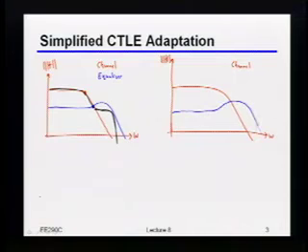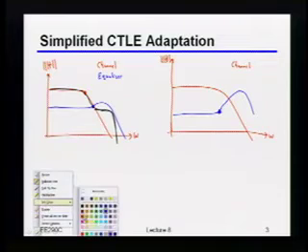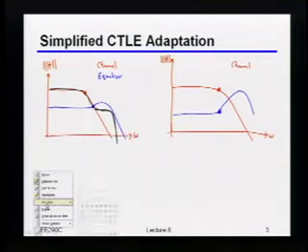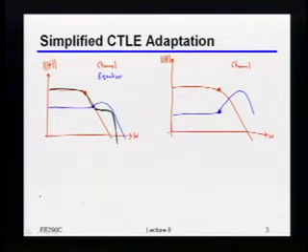The equalizer will now look something like this. There. In other words, that's the 0 of the equalizer, and that's the pole of the equalizer. Okay? All right, so now my equalized response should basically just look flat, right? If I do it properly, then the magnitude will be lower than the previous case. So it should look something like this.